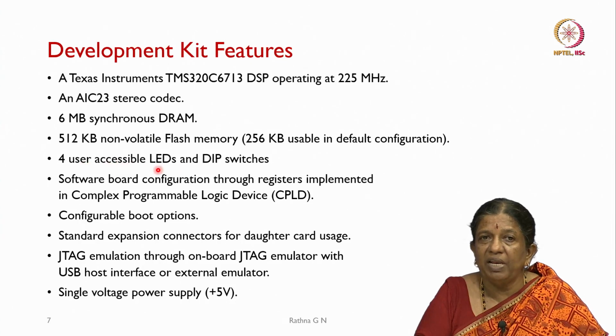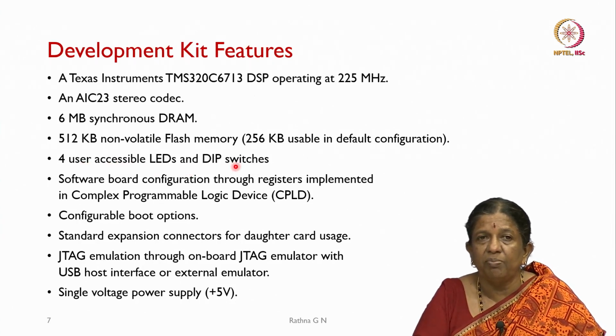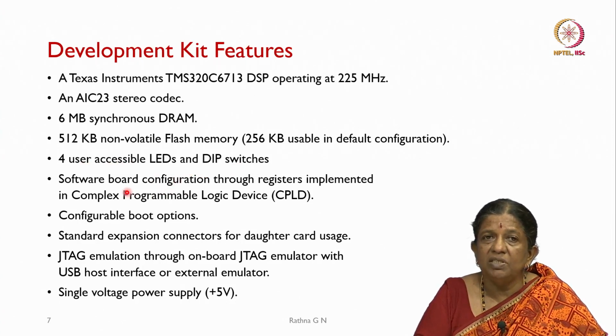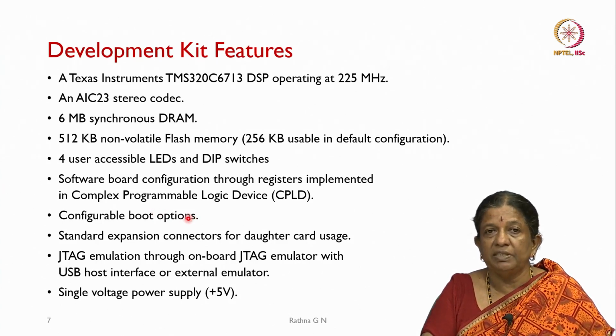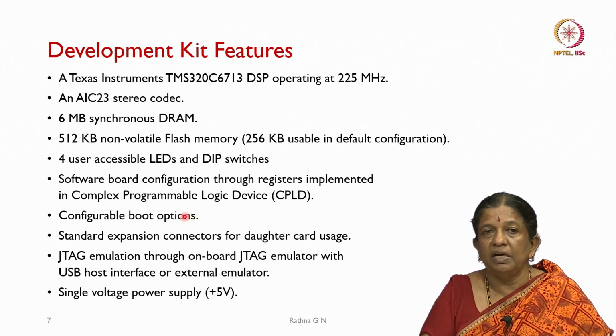We have 4 user-accessible LEDs and DIP switches which can be configured depending on our application. And we have software board configuration through registers implemented in a complex programmable logic device, that is the CPLD, and we have configurable boot options. Once the system is booted, it can run on its own once power is given. So, it can continuously take the input and provide the output.